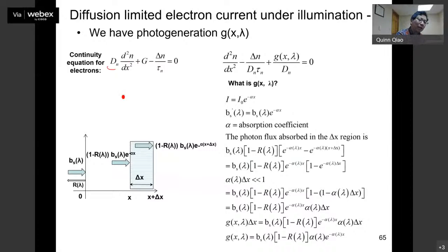Then on the p side, the diffusion coefficient of these minority electrons, and also their gradients, the gradient of the equation of that minority electron. And this gives you the diffusion rate, how fast the electrons diffuse. And then you have generation. What does the generation mean? Generation means under sunlight you generate extra carriers. That is different from the electrons injected from the inside. Now since you have a lot of extra electrons and holes there, you have a recombination rate.